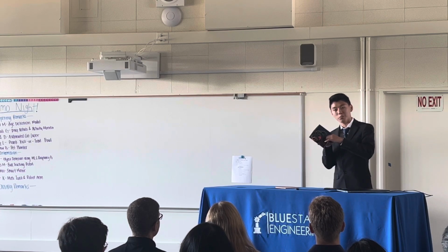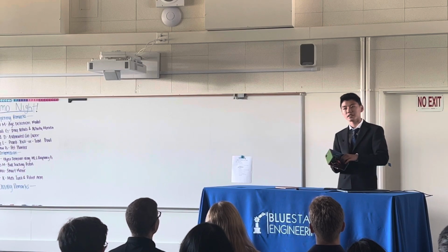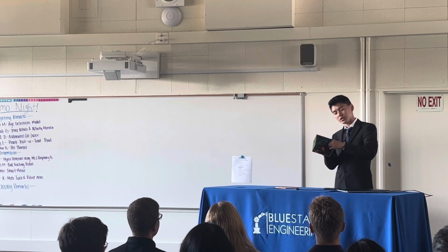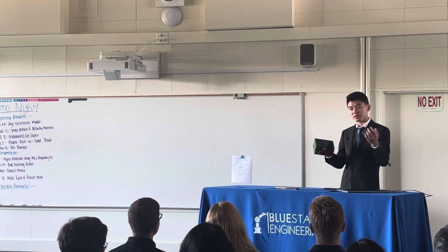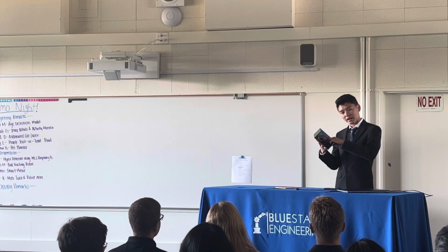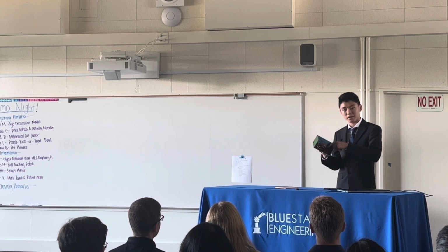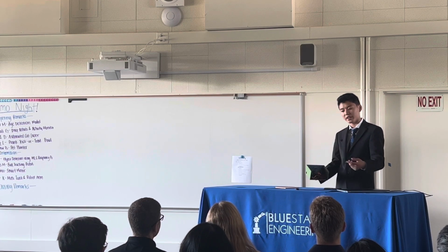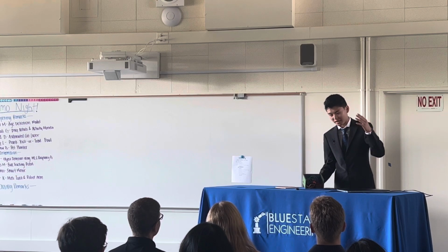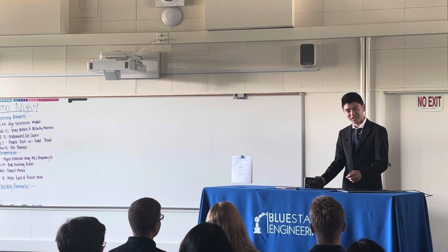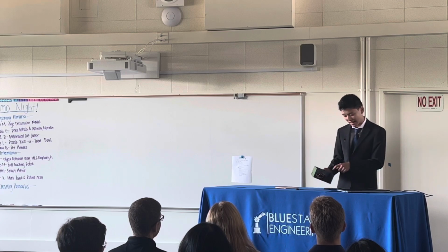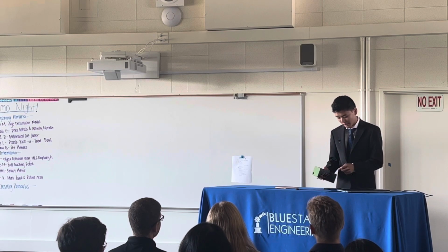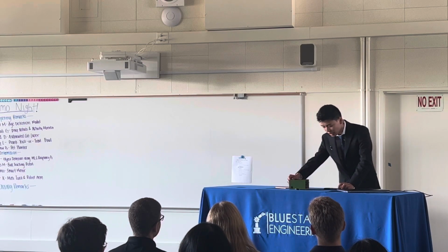This is not a toggle button, actually. This is a hold down button, meaning that if you hold it down, it returns an on state, and when you release, it's off. But I wanted it so that if I press it, it just turns on, and pressing it again turns off. So I had to create 4 different if statements and about 10 different variables in order to create a toggle button out of a hold down button. And the LED here is just an indicator.